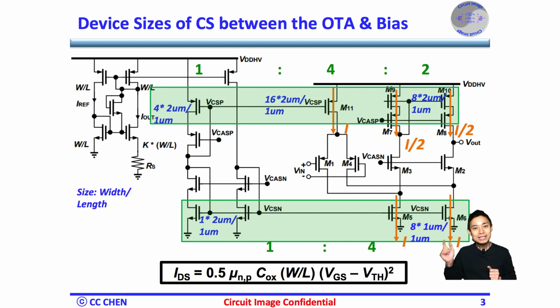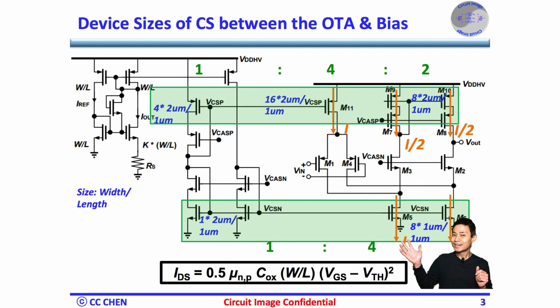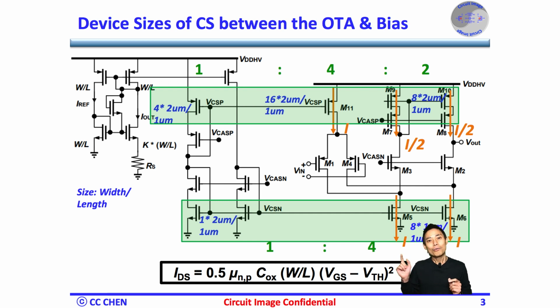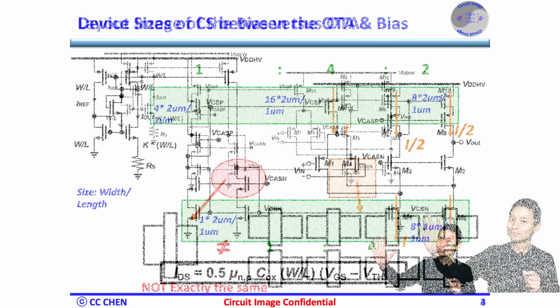But do you see the unit size of the NMOS isn't the same even though the unit size of the PMOS is the same? Do you see any total width issue from the current equation here? Probably not, since the ratio of the total width is correct, no matter what the unit width. Could you please think about the unit size layout images for 5 seconds?